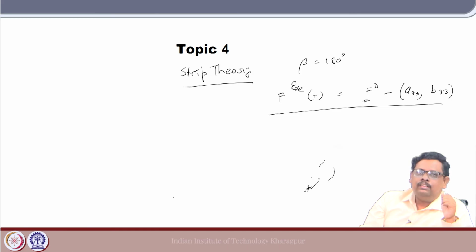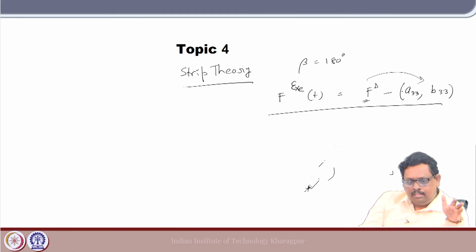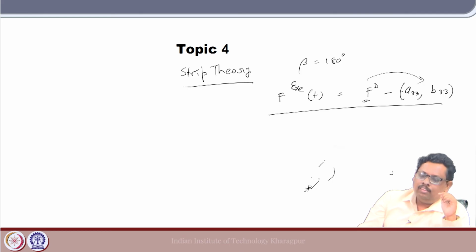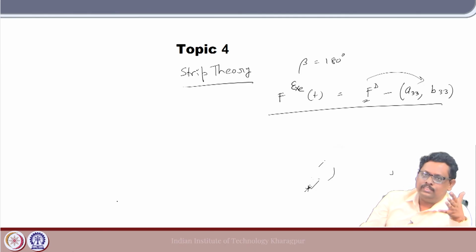I gave you one homework to develop a strip theory code assuming simplistic head waves, with the exciting force, the diffraction, written in terms of added mass and damping, which you can get from the Lewis curve. Also, if you remember, we discussed how in a simplified way we can write the exciting force.